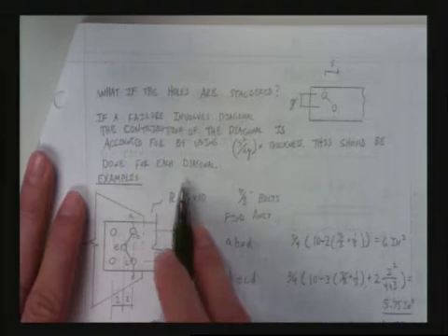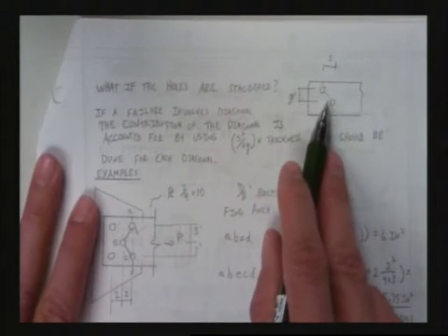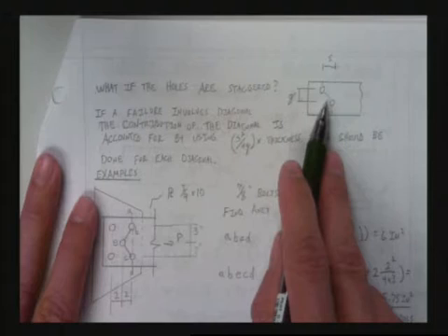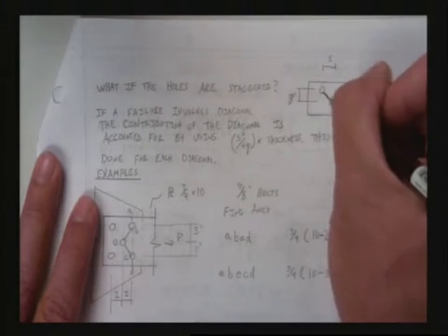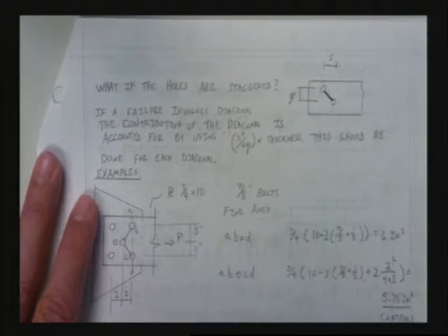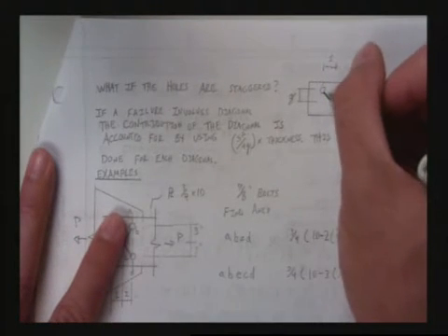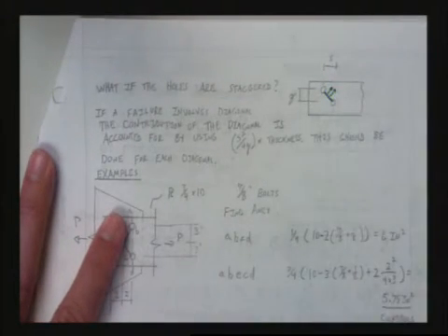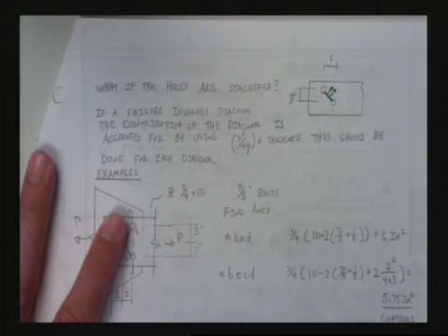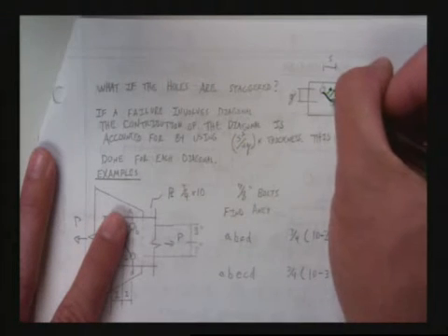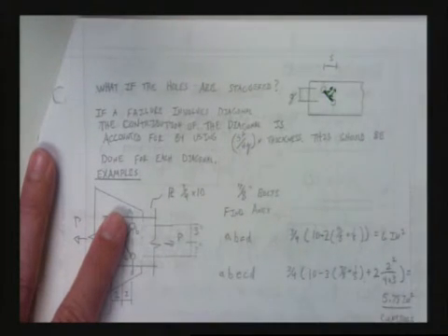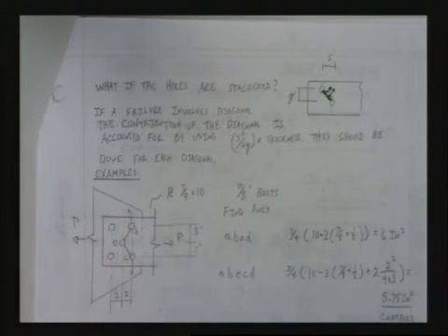And why do we do this? Well, it's because simultaneously on that cross section, we have tension and shear occurring. So we're not able to get away with just the pure area. If you just took the pure area and treated it as failing in pure tension, that's not conservative. And if you took the full area and treated it as failing in shear along the length, that's too conservative. So this s squared over 4g is something in the middle.